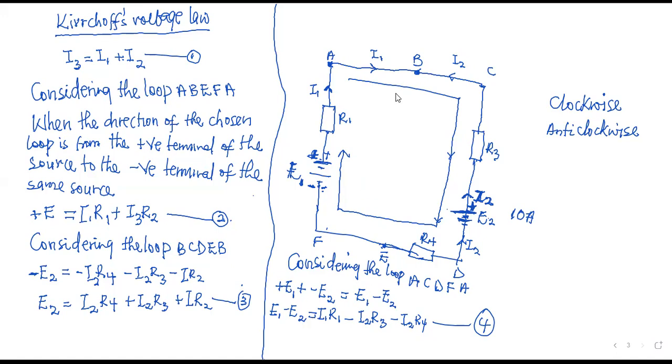All right. Please note that this illustration is based on the fact that we consider the internal resistance of the batteries or the cells to be negligible, 0. If you are given the internal resistance of the battery, you must also consider the lost volts, so the volts that will be dropped by the internal resistance as well. Factor that into the circuit. But this is on the account that r is equal to 0.